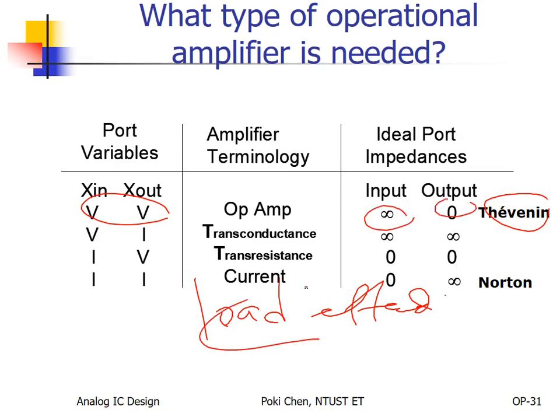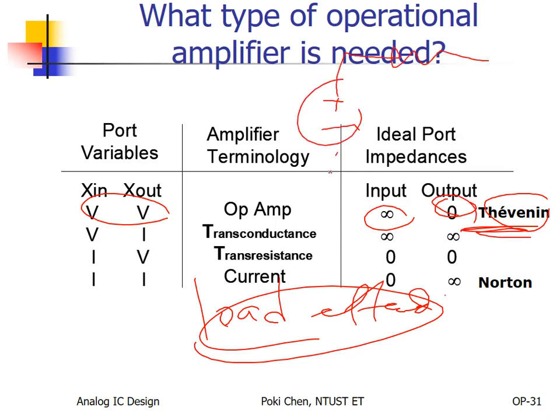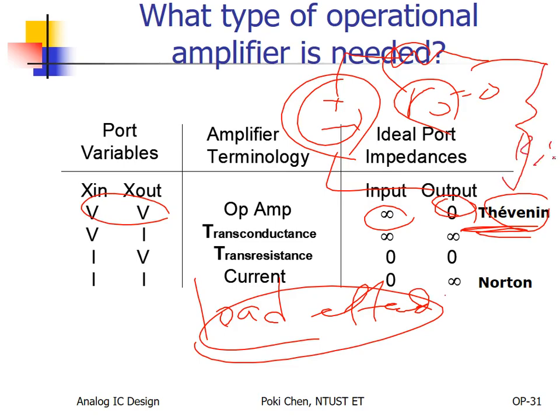And again, for the load effect, we hope we push all the voltage to the output. So we hope our own output resistance is 0, as small as possible. According to, again, Thevenin, that is the output. If you are the driver, then we hope this is equal to 0. If you are the load, the input stage, we hope this is infinite. That is the very simple idea.